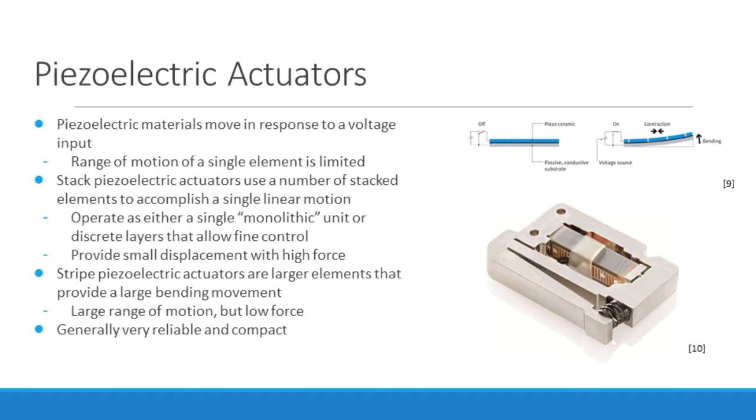One type is the stack actuator, which uses a number of piezoelectric elements arranged in a stack to provide a single linear motion. They can be controlled such that they produce a single unified actuation, or as a number of discrete units allowing for a wide range of positions and forces. In either case, they usually provide high force and low displacement.